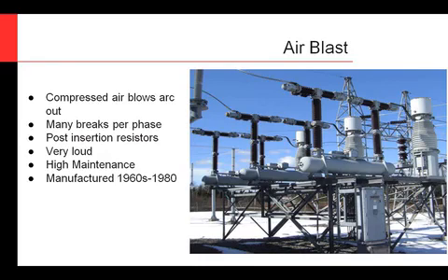They're very loud. When these things operate in the substation, you know it. I've seen, just from the cabinet where the air was not properly vented out of the mechanism, I've seen cabinets blow out and different things from this. Same thing, manufactured 1960s to 1980, no longer in production, it was once again replaced by SF6 style. High maintenance, so these are once again being opted out and replaced with your SF6 circuit breakers.